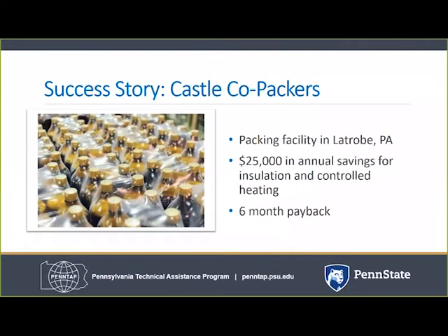PennTAP visited the Castle Co-Packers facility to assess boiler combustion efficiency, evaluate heat loss from uninsulated piping, and find opportunities to recover waste heat. Based on PennTAP recommendations, Castle Co-Packers would be able to save $25,000 per year in natural gas costs, with a 6-month payback on their investment.